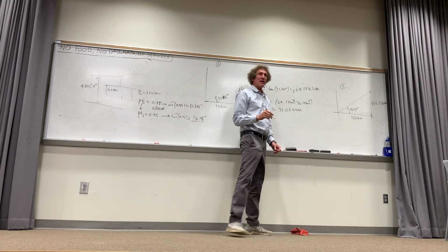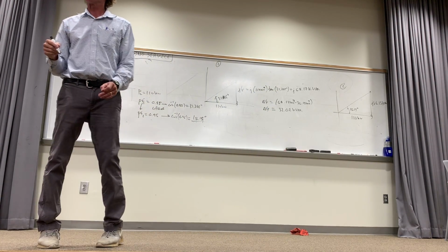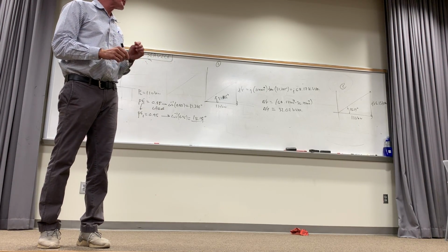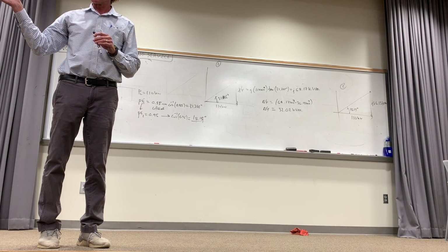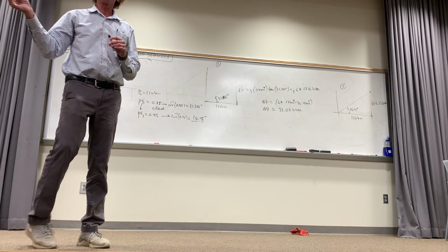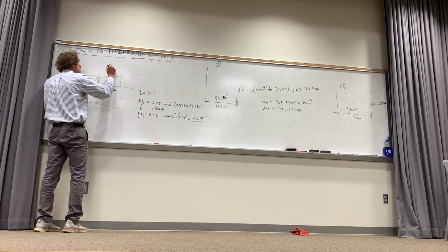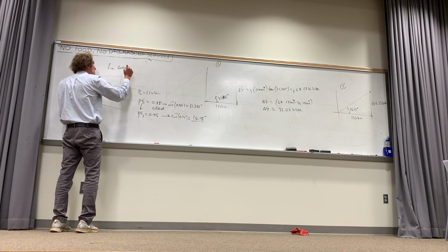All right. Now, how are we going to reduce it? We're going to add a capacitor that has negative 32.02 kVAR associated with it. Is everybody following? The one thing I didn't give you is the frequency. Almost inevitably, everything works at the line frequency of the power company. Our frequency is 60 hertz.